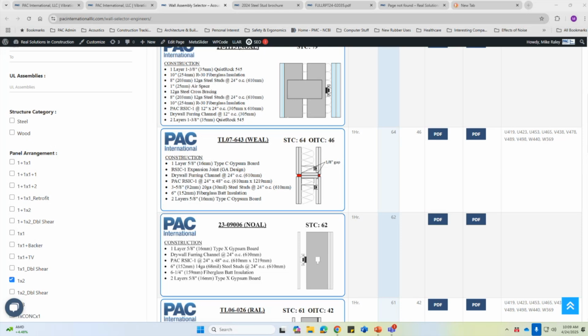Okay. And there are just three comments, if I may. One, when you talk about a sound-rated door, I prefer to say sound-rated assembly, because people buy doors that have a sound rating, but you need the frame, the seals, the hardware, and the threshold to get what you're paying for. This is very true. That is a great point. Doors were not the primary emphasis of this, but that is entirely true. And same thing for a window. I have seen for some windows, you'll just get testing for the glazing itself, and it doesn't include the frame or any of those kinds of things. That's a very important point for people to pay attention to.